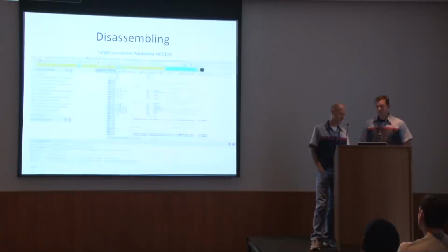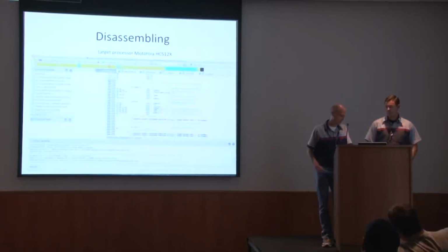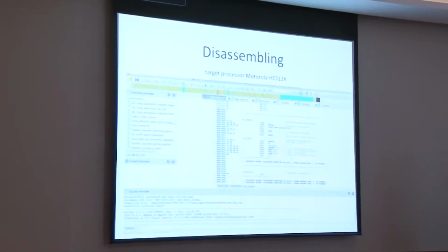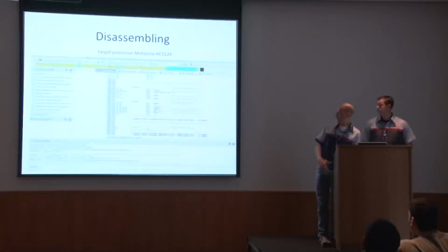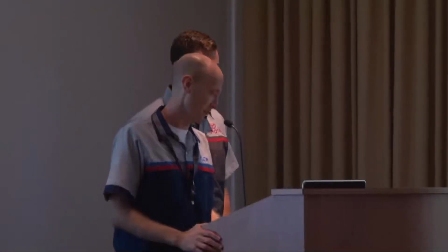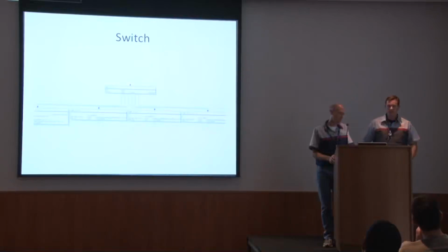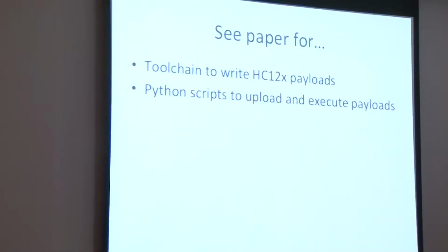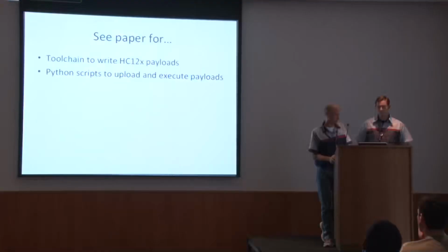So I used this HC12 development kit. And then once I had firmware, there was actually already a module in IdaPro to disassemble it, so that made it easy. I disassembled the whole thing, and I could figure out how it worked. It's pretty easy in the embedded world to reverse things because there are particular things in hardware that tell you exactly what's going on. So you know at some particular address, that's where the CAN stuff happens. And so it's pretty easy to reverse out where all the interesting CAN things are. You can find the big switch statement that handles it and so forth. So check out the paper if you want to see more information about that.